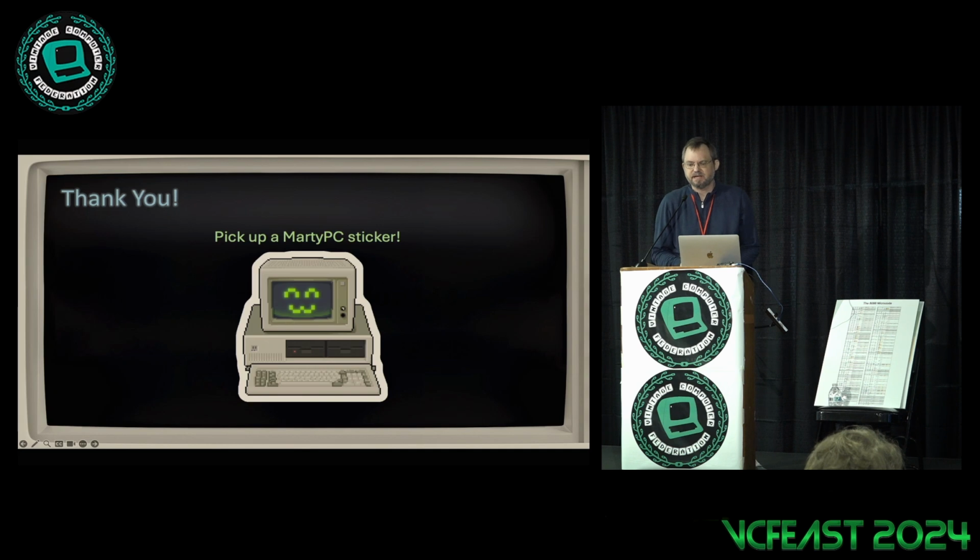So an Intel 8088 version doesn't run under the validator board because of the clock rate. There's a minimum clock rate. And it's interesting the way it fails. It looks like it's running perfectly fine. It will do EA address calculations, but if there's a displacement, it sets the displacement to 0. That's the only thing it fails to do. It'd be fun to try to program around that limitation. But the AMD D8088 is still an NMOS chip, second source. And from all the sources I read, there shouldn't be any differences, and it runs just fine. That's the one you saw there.